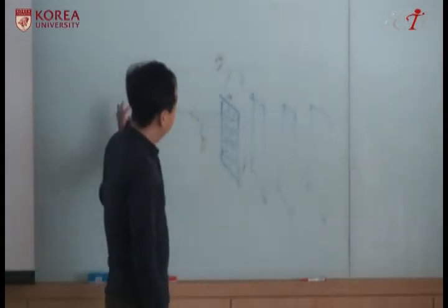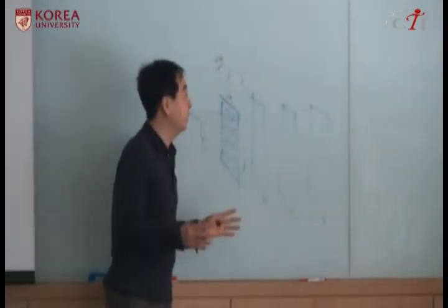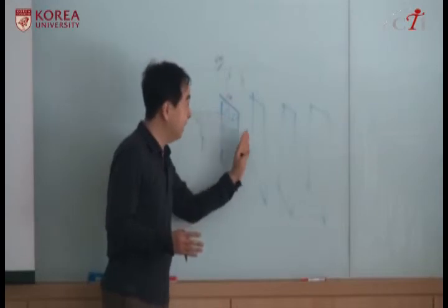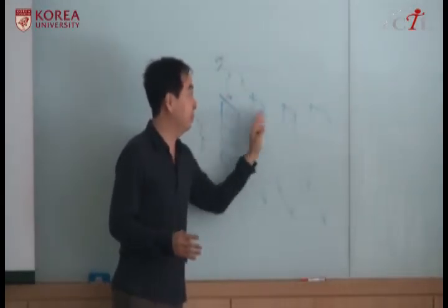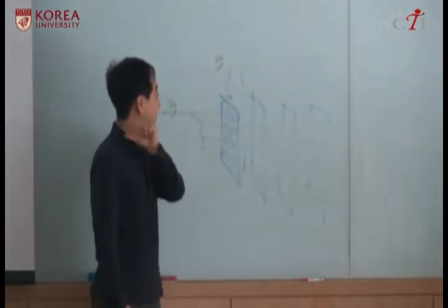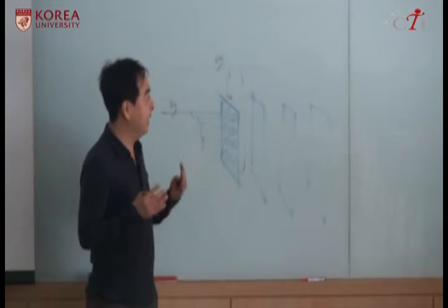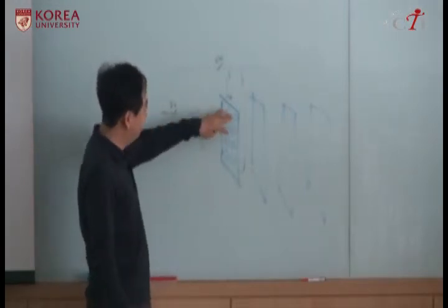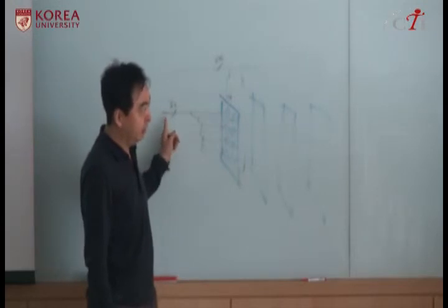And when the CPU accesses one DIMM, the other DIMMs are inactive. One active at a time. So it's not proportional to the number of DIMMs. What the author is arguing does not make sense in my idea. It's more the number of chips that are connected to your address bus line.